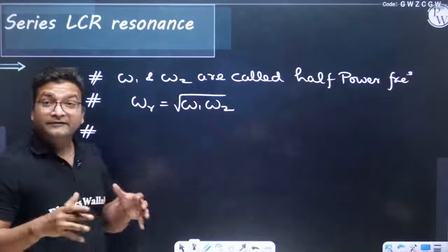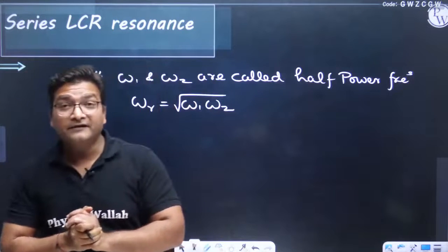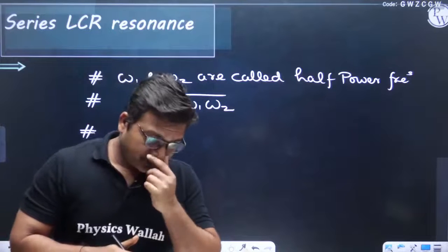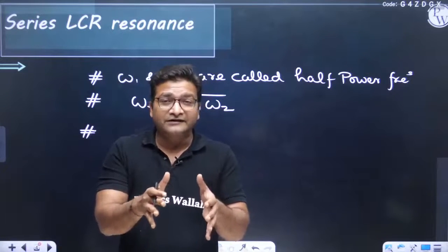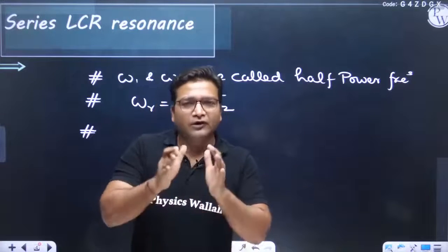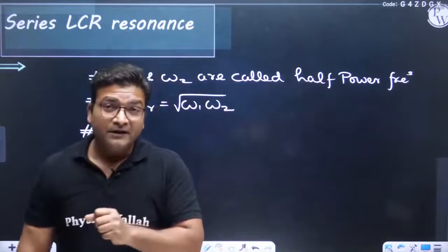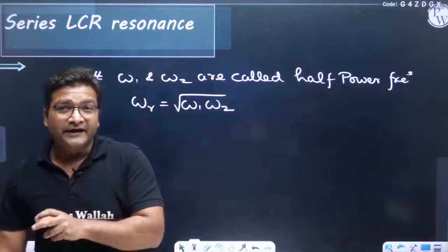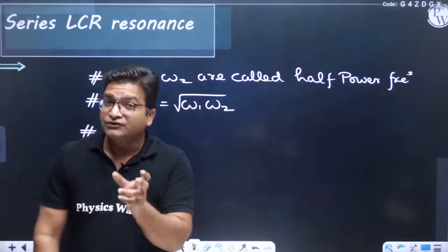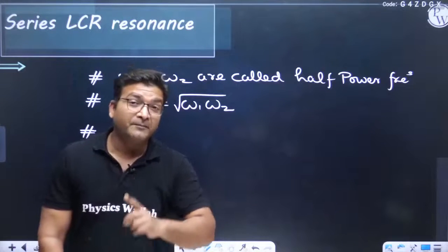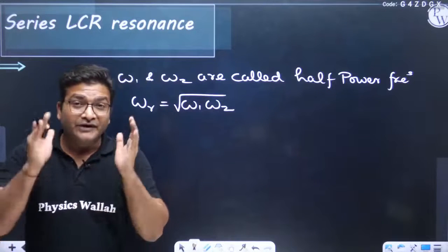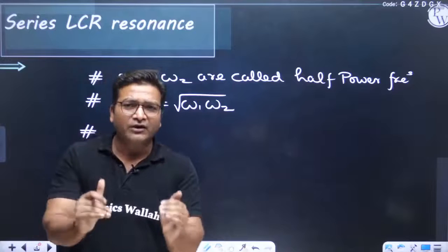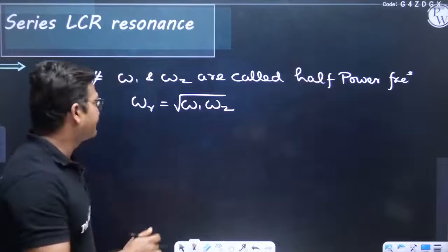As the circuit is in resonance, remember, the voltage across the capacitor and inductor has the same effective value, always the same. Why the same? Because XL equals XC, and if XL equals XC, VL must be equal to VC. But remember, by phasor, VL and VC are in opposite directions, so the effective voltage across L and C is 0.